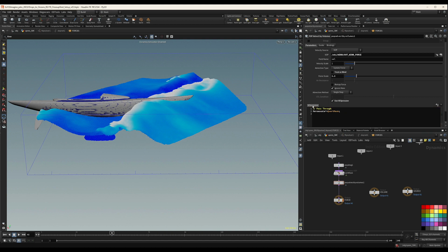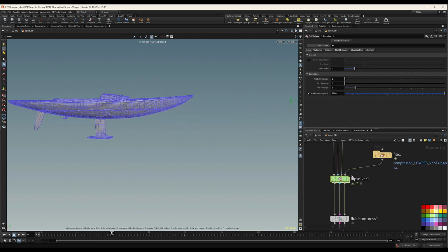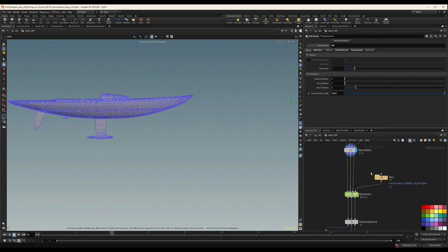Okay, so I'm multiplying the force scale, this number, by 0 to 1. So everything that does not have a lot of vorticity is not going to be influenced by this wind. Everything that has a 60 or more is going to have full influence of the wind. And that's it. We have set forces inside our solver, so that's how you do it.